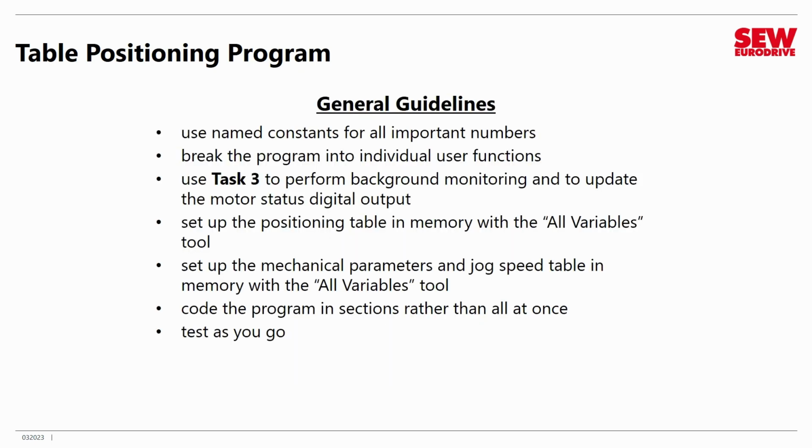2 final guidelines. Code the program in sections. Don't try to write it all at once. Set up the variables and the constants, set up the main and the initialization and the background task, then set up the dispatch code, that kind of thing. Do it piece by piece and certainly test as you go.